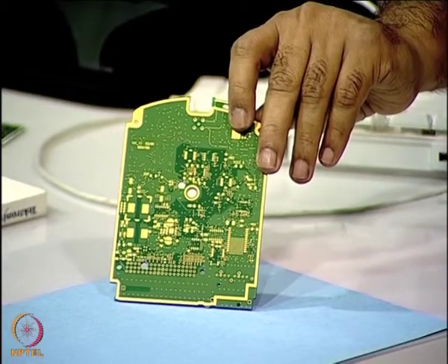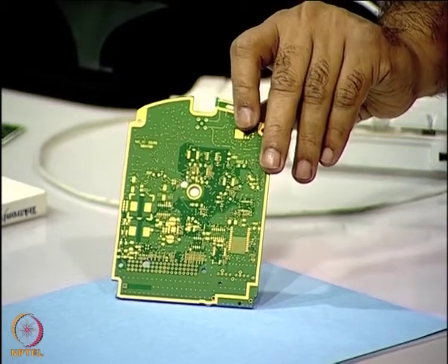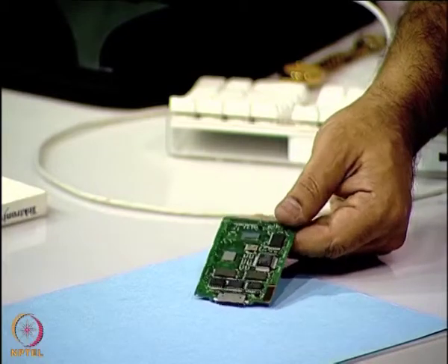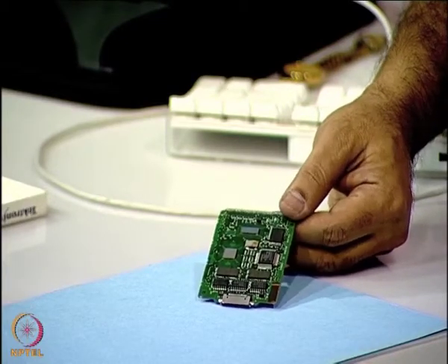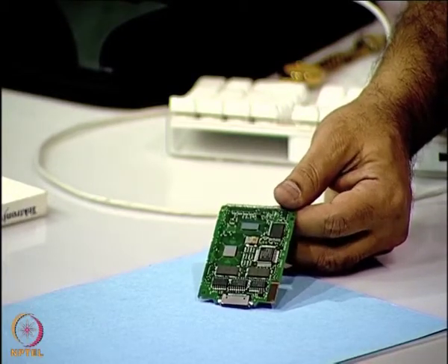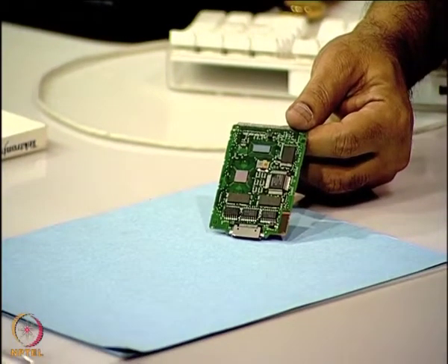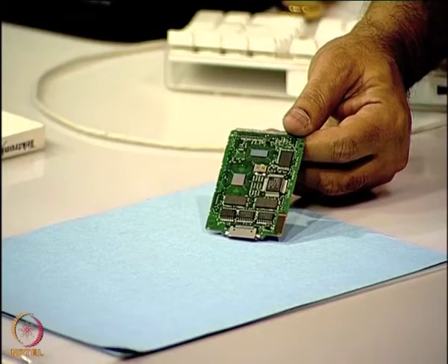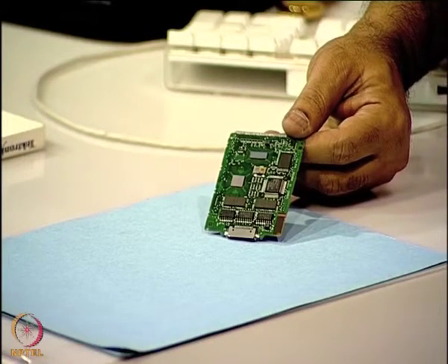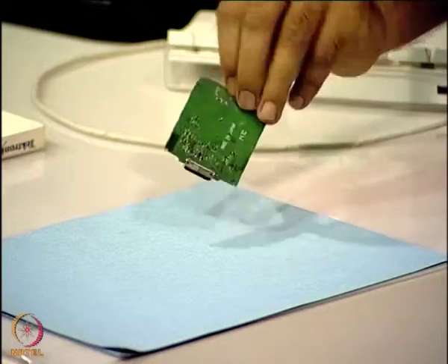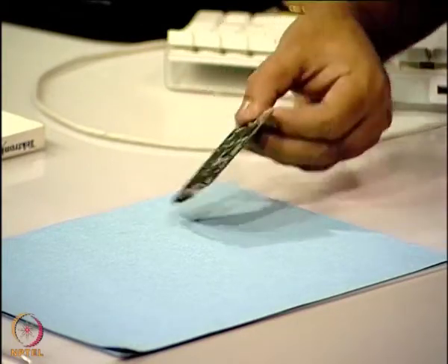This is a high density interconnect structure. Now, you can also have another kind of high density interconnect structures, as you can see here. This is an 8-layer sequential build up high density interconnect board. You can see advanced packages like a BGA and a flip chip, a lot of QFPs, surface mount resistors have been mounted and both sides have been utilized.